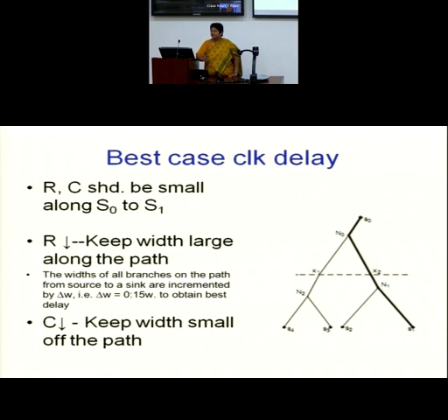T is usually set by the technology chosen. Okay, so TSW I have taken care of. Now there is another component called TSB. B comes from buffer, because I would be inserting a buffer over here. So my total delay is not only because of the segment, it is also because of the addition of T buffer. Now if T buffer is mismatched, I will get a skew. So this T buffer skew should also be within bound.